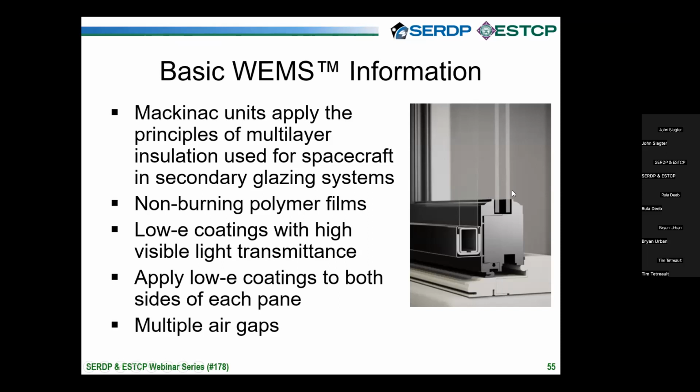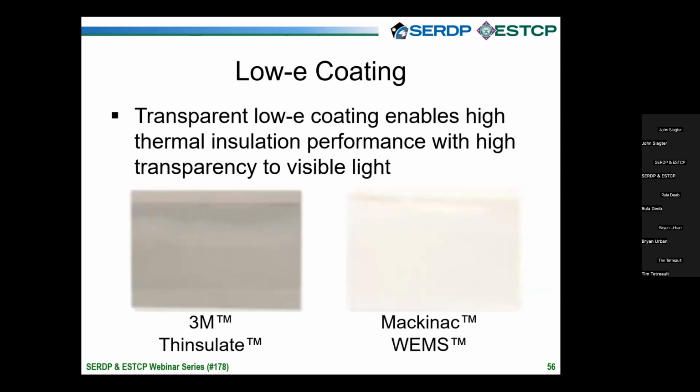It's to understand how heat transfer through windows works. 2/3 of the heat transfer is by means of electromagnetic energy, and 1/3 is often attributable to conduction or convection. So if we attenuate the infrared heat transfer, we're left with conduction and convection. And in our products, we have 2 gaps here of stagnant air, which has a really good insulation value similar to styrofoam. And so that's how we're able to get a really good insulation performance without needing to use argon or inert gas.